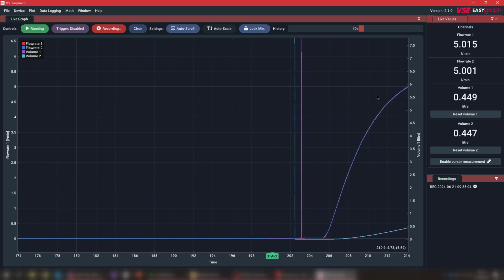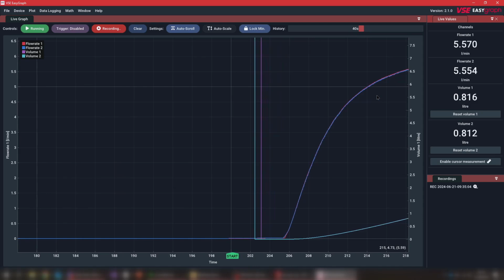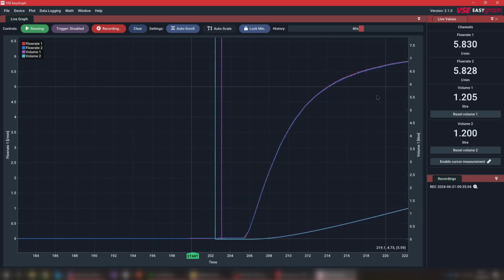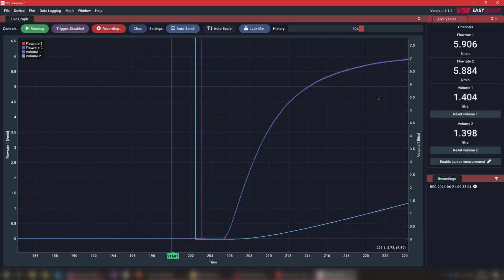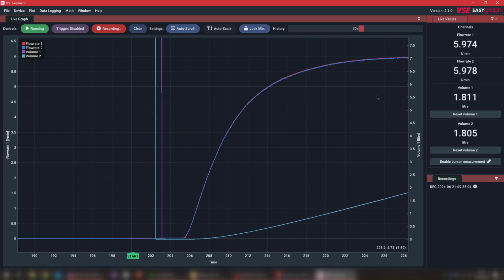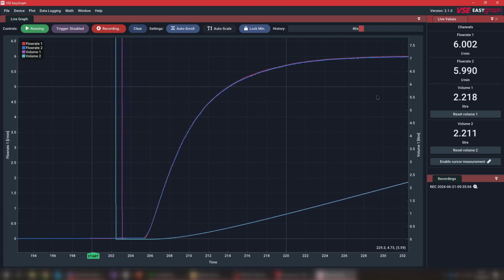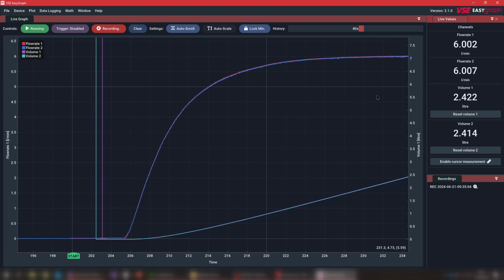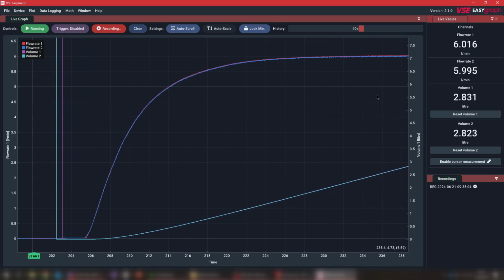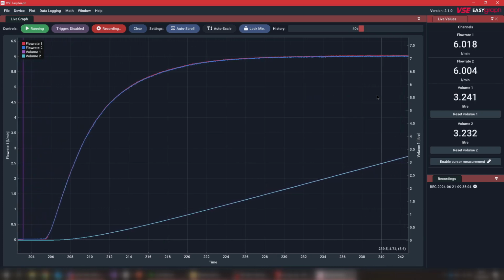As both flow meters are in series, you will see both lines behind each other. So the master flow meter will be the red line and the blue line is the device under test. And at the bottom in the cyan and purple lines, you will see the volumes going up. So now the flow is stabilizing and the actual calibration is going on in the background, and after the point is measured, we will see the flow rates go down again and approach zero flow again.